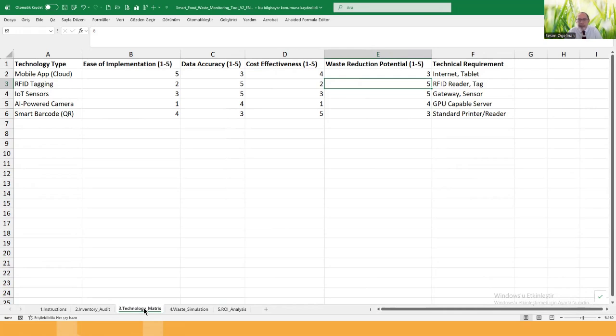First, the technical specifications of the IoT sensors required for cold chain tracking are analyzed. A selection is made based on criteria such as battery life, data transmission distance, and measurement precision tolerance margin, etc. For example, while high-precision Bluetooth Low Energy sensors are preferred for fresh dairy products, the NB-IoT narrowband IoT protocol is evaluated for the wide coverage required during the logistics phase.